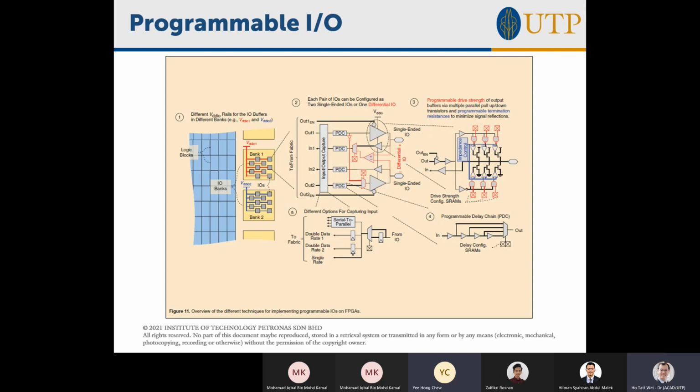So I'm just letting you know, logic 1 does not just mean it's 5 volts or 3.3 volts. That's very old already. There are a bunch of standards where it can be defined by the supply voltage, the VDD. The typical one is 5 volts for TTL, 3.3 volts for CMOS, 2.5 volts, 1.8 volts, 1.1 volts, and there's even lower. Then there's what we call low voltage differential signaling, LVDS, where the voltage is just 100 millivolts, but you need 2 wires because they are differential signals.